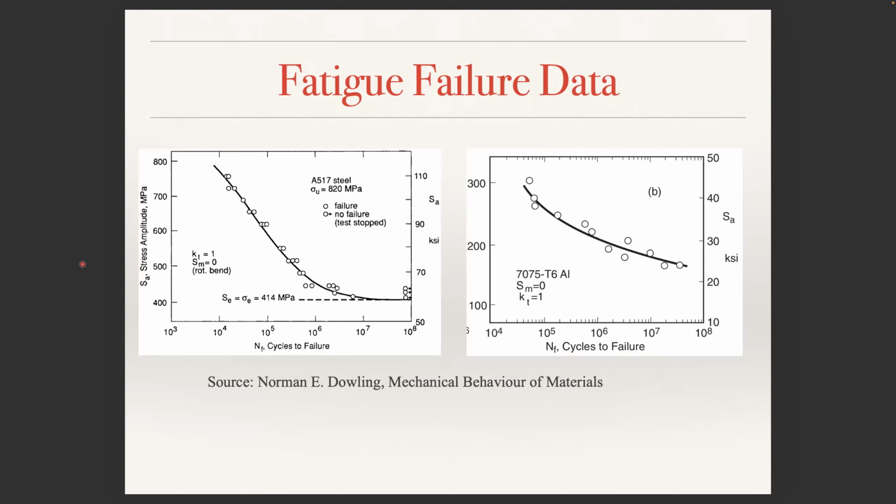Okay. But in reality, the components are subjected to some mean stress. That is one thing. And the rotating beam bending test is usually done at room temperature, but in reality the components may be working at a different temperature. And this test is done on a specimen of certain size, but in reality, the specimens will be of different sizes. So there are some variations from actual service conditions compared to the specimen condition, test conditions and specimen geometry that is used for producing this data.